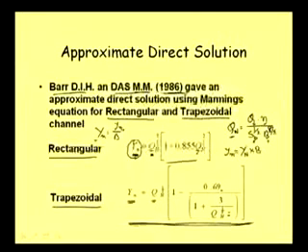Calculating this Qn with the given Q, given n value, given bed slope and given width of the channel, we are calculating this Qn, and then the z value we are using whatever is given. This z value is basically 1 because our slope is 1:1. So we use z as 1, and then we calculate this yn.